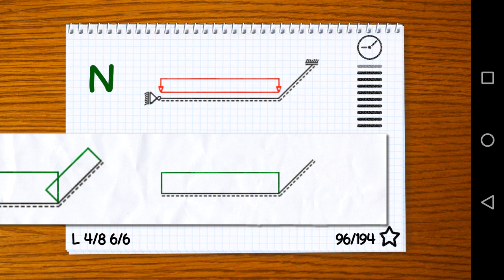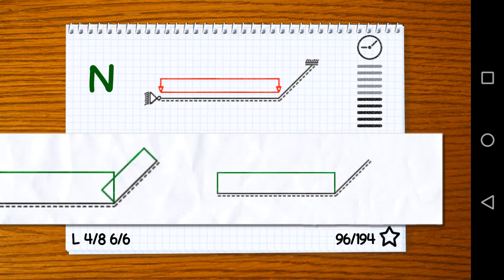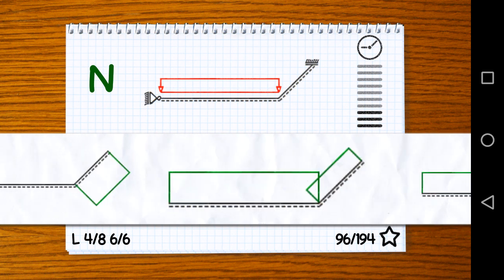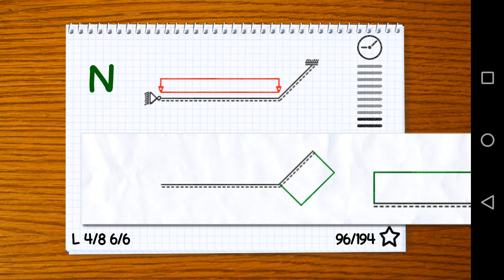With some of the force in the vertical direction, we figure out that at the parallel motion we have an upward force leading to tensile stresses, leading to tension, let's say, in the inclined element. This answer here says 0 normal forces in the inclined element. This one says compression in the inclined element. Here's the right answer with tension in that inclined element.